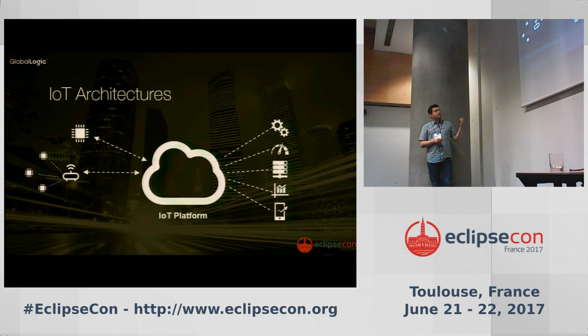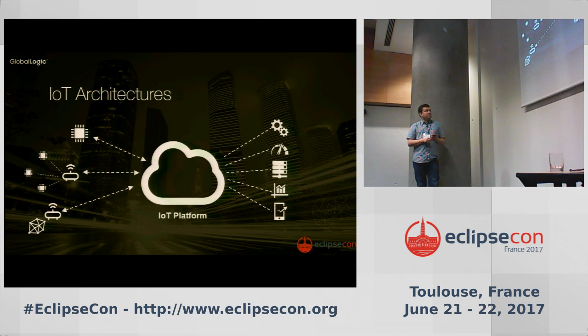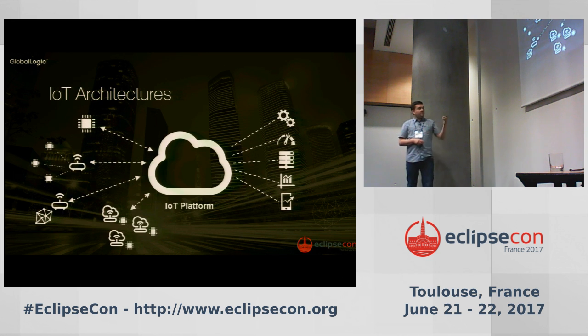The second thing is that we can have a local gateway and direct connection to the devices. The third one is that the gateway is connected to some kind of network. Like in our case, this is the Modbus network, where our gateway is connected to the PLC using the Modbus network, and we are gathering the data. Of course, there could also be a set of gateways. Each gateway is connected to one device, just to have a facade in front of, for example, a flow meter, or in front of the PLC.